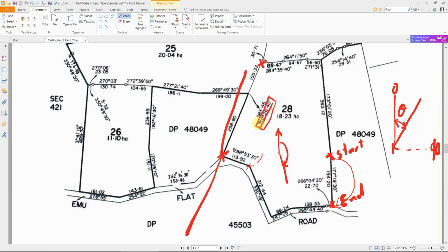What we have to do is what we call reverse bearing. That doesn't mean it's wrong. What happens here, guys? For this particular line, it looks like the surveyor started from, for one reason or another, maybe for the first day they finished all of those, they left for that day, they came the next day, they started on these lines here. But for this particular line, he measured from this as a starting point, and that's the direction, this is the end point. As long as I realize this line and that line are not the same direction,